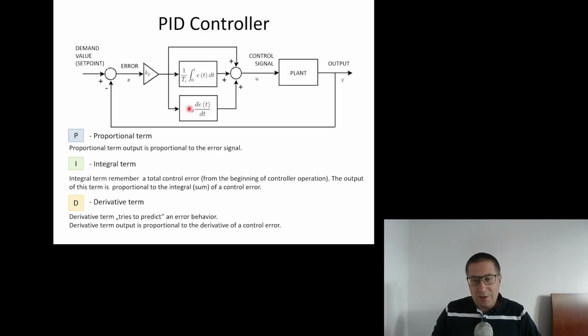And of course, if we are implementing the AI method that, I don't know, optimizes the plant or the factory, it usually changes the set points. So the AI algorithm usually changes the set point for the temperature, the set point for the flow, the set point for the device load, not the control signal itself.